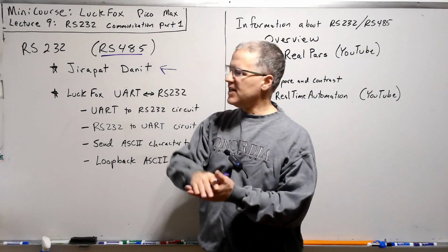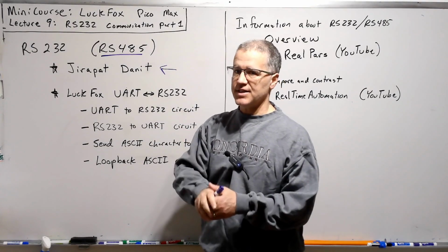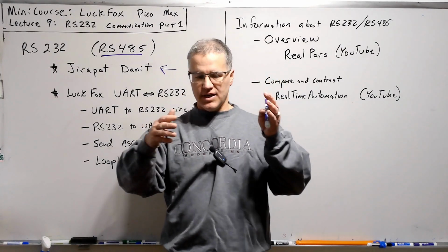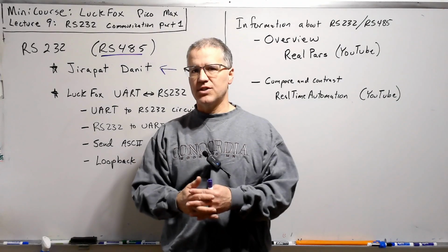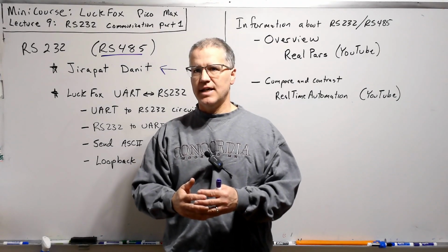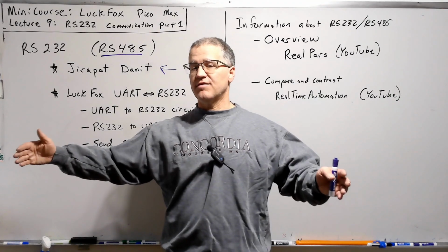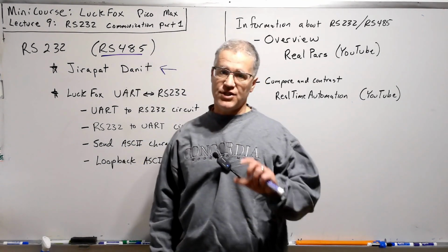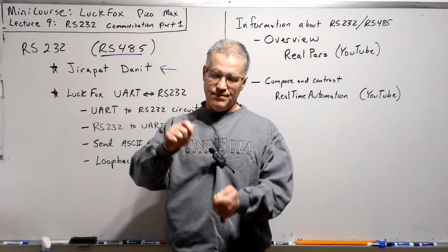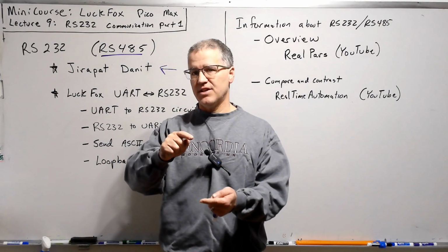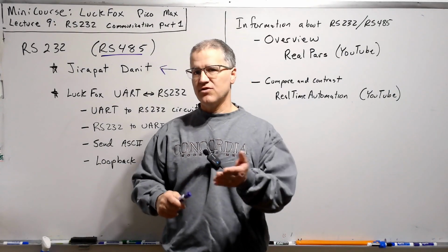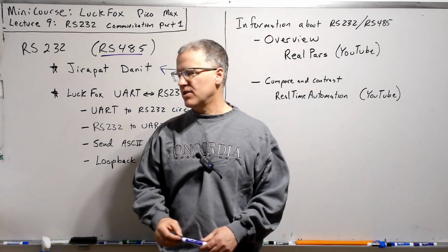One of the disadvantages of RS232 is that it can be susceptible to noise. Another disadvantage is that you can only plug in one device between the two. And another disadvantage is you can't string a very long cable. So along came RS485, which addressed these. It builds its communication based on a voltage difference rather than -9 volts compared to ground and 9 volts compared to ground independently.